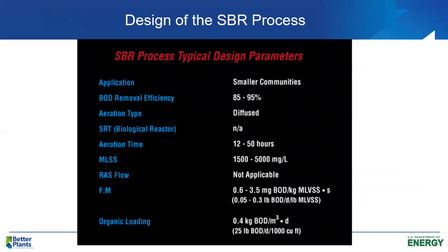As I said previously, it operates in the extended aeration mode. We'll have detention time on the order of 24 to maybe even 48 hours. Most of the plants I'm familiar with have about a 24-hour hydraulic detention time. They typically operate at 3,000 to 3,500 milligrams per liter mixed liquor solids. Again, a fairly low F/M ratio, long sludge age, and the organic loading tends to be low because it's low rate activated sludge.